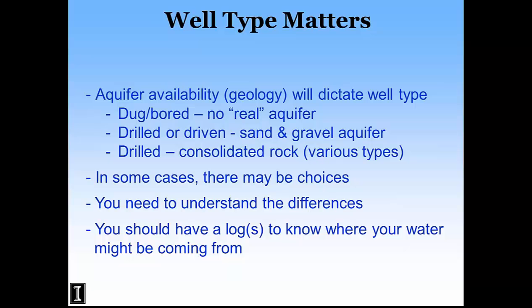In some cases, you live in an area in Pennsylvania, a lot of wells are bedrock wells, for instance, that have very low water yielding capacity, maybe a few gallons a minute. That's the only choice you have because that's the only material that's available. There's places in Illinois where you may be able to drill through 50 feet of sand and gravel and put a well in if you want, or if you decide to go deeper, there's a very good bedrock water supply as well. So you have multiple choices.